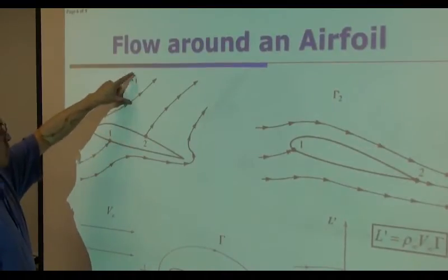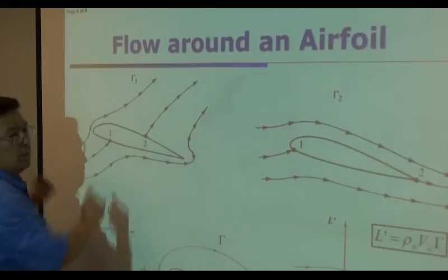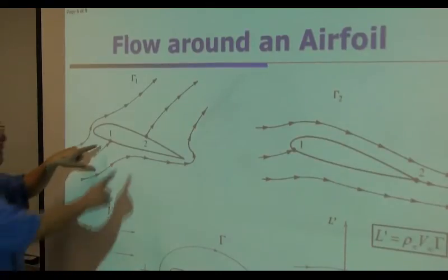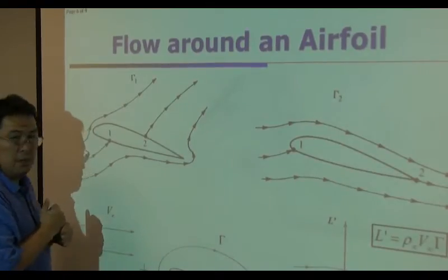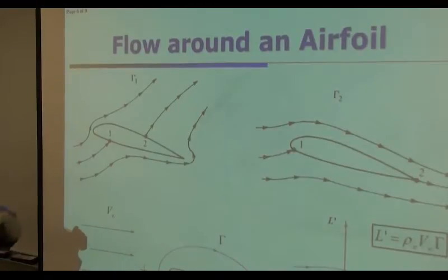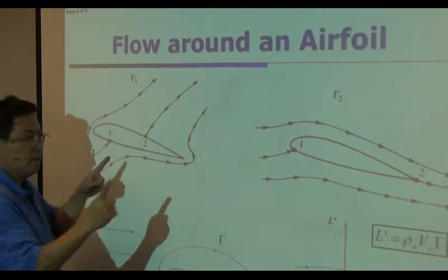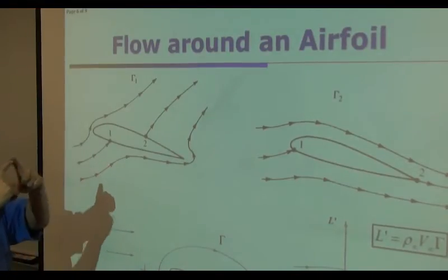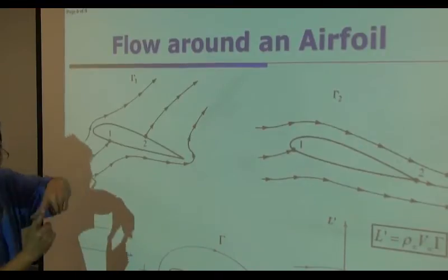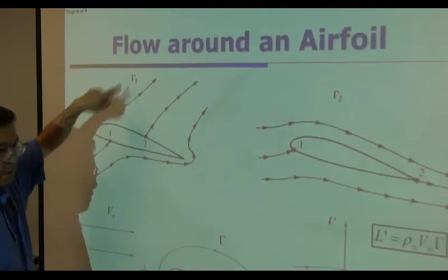So that is going to arbitrarily determine two stagnation points on the surface, such as we observed in the flow of a circular cylinder with a certain amount of spin. The location of the two stagnation points over the surface depends only on one thing. What is it? How much spin you have, which is circulation.